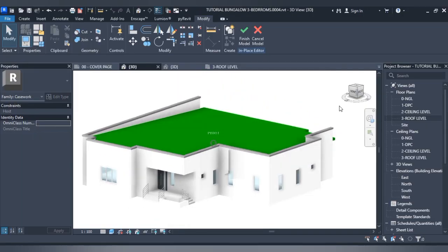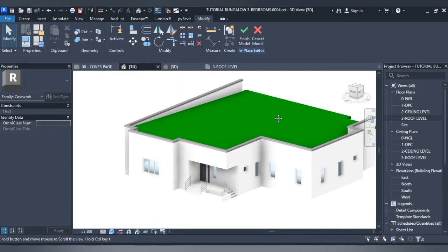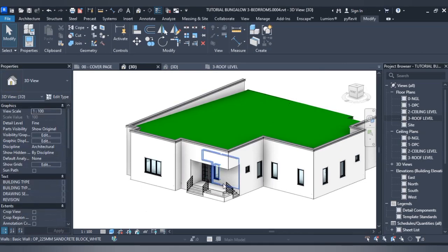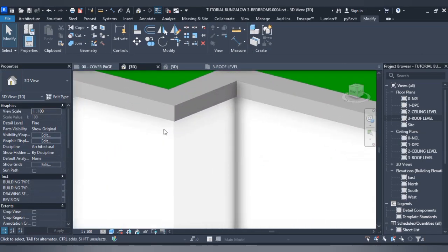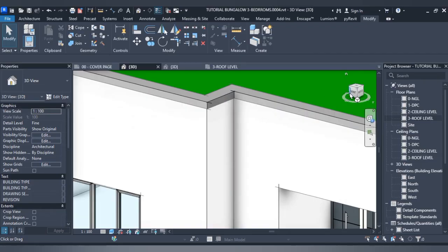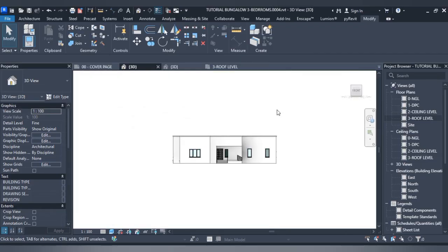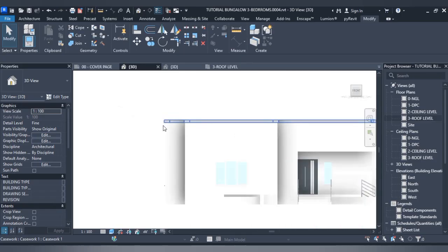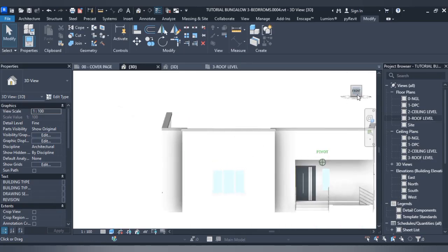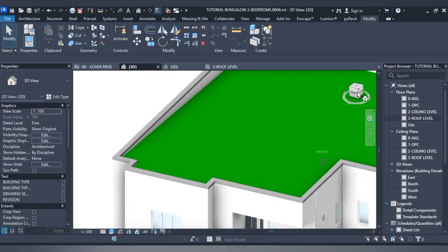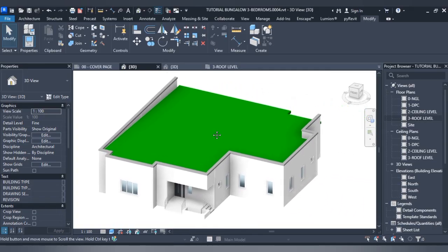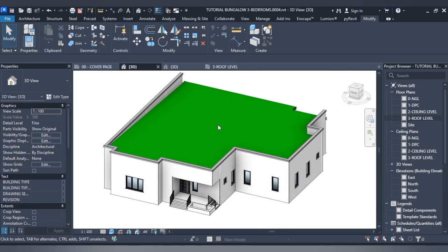So we'll add a material to this later on, but let's just keep on modeling what we want to actually achieve. Let me finish this so we can see the capping right here. If you change this perhaps to look like an elevation, you're going to see the capping with that little bit of a projection. It's going to be protecting the wall from rain and drops and all that, so the wall will not get damp. So it's us thinking construction-wise here also.